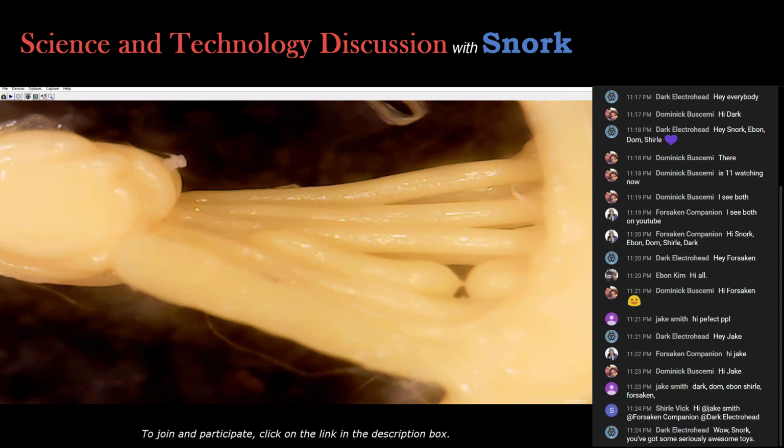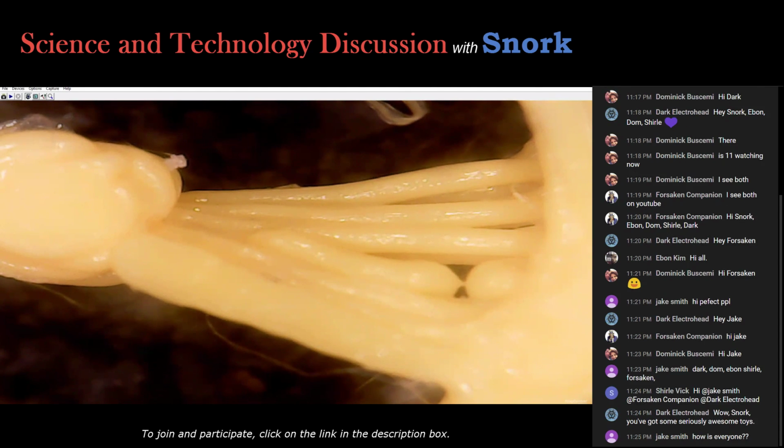There are other methods of 3D printing. One starts with a goo that is UV sensitive, or ultraviolet light. An ultraviolet laser hits it, and where it hits on the surface, it turns into a hardened plastic. And it basically just keeps going, sinking. Your model sinks into the goo, a new layer of goo flows over, the light comes back, and it makes another layer.